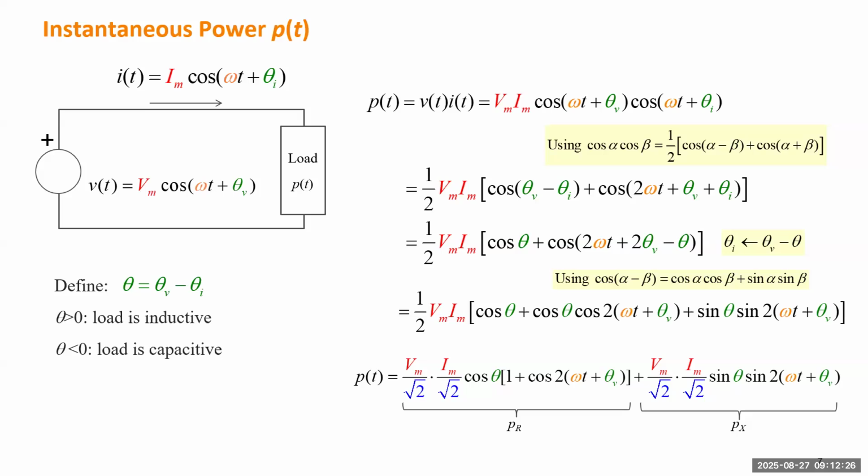we want to use the RMS value, the root mean square value, for voltage and current, because they are more meaningful values related to power. This expression also involves the angular frequency of this AC circuit and the voltage angle, which is relative to the revolving reference.